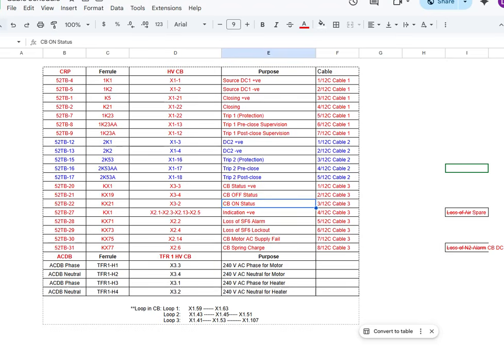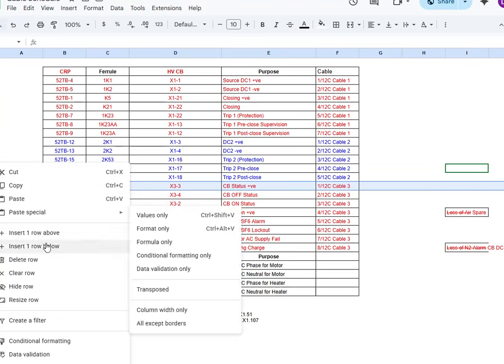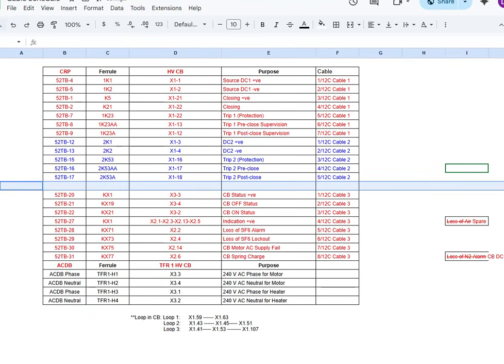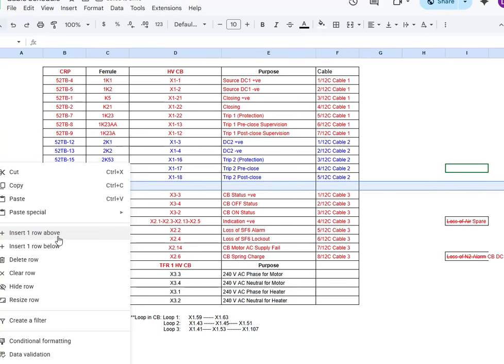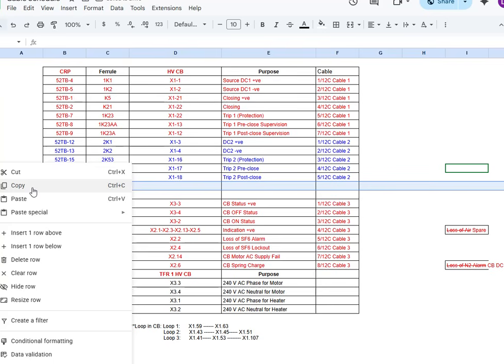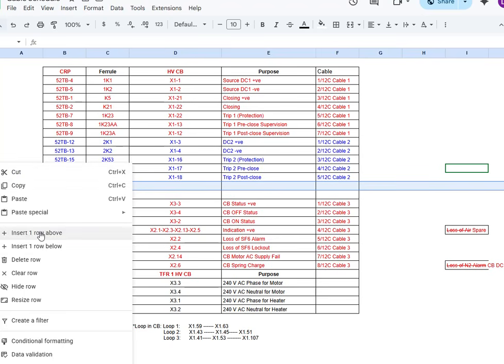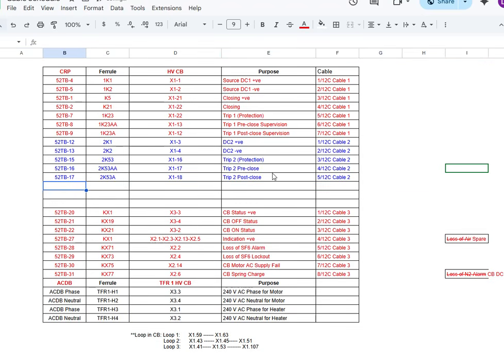We'll use cable 2 for wiring up the initiation indication, but we'll keep it on the spare TB for now. On the relay panel we'll keep it on the spare TB: spare 1, spare 2, spare 3, and we'll give it common.